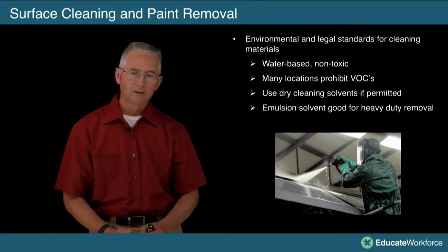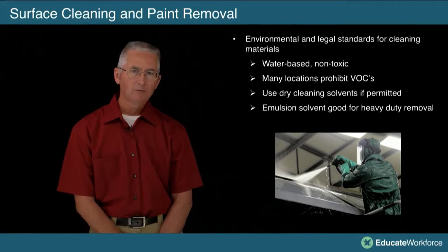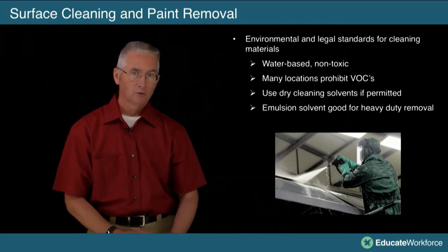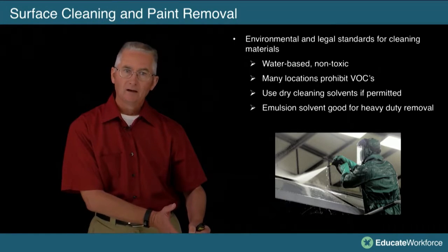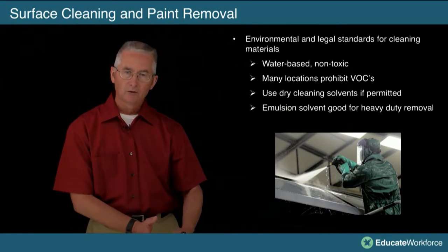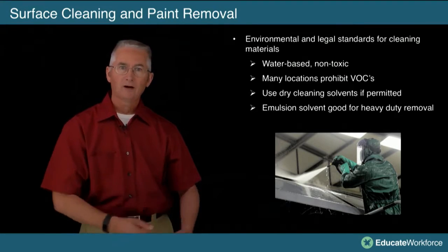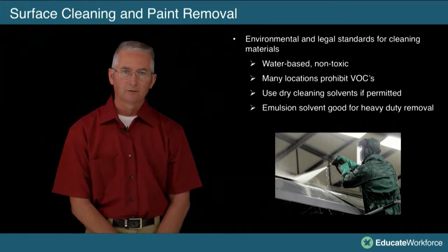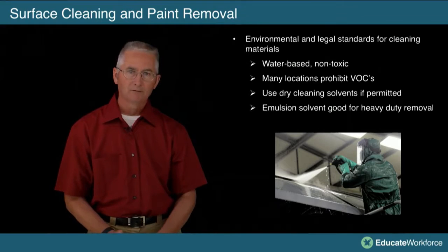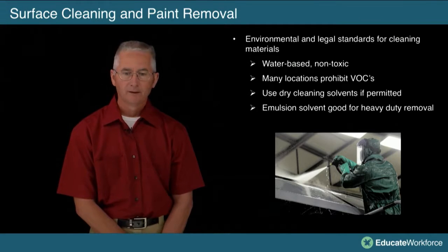Third, and one of the things you need to remember, you get a water-based, non-toxic paint remover, but what are you removing? Paint, oil, grease. Is that all toxic? Could be. How are you going to get rid of that? Again, this is where you should have some established rules. There should be some regulations you're following. You just don't want to remove all this paint and then throw it in a trash can, or you could get a visit that you're really not looking forward to. So follow the EPA rules. When in doubt, ask. Your shop should have some type of policy that says when we do this, this is how we get rid of our hazardous material.